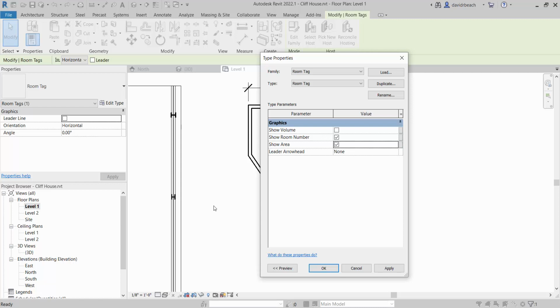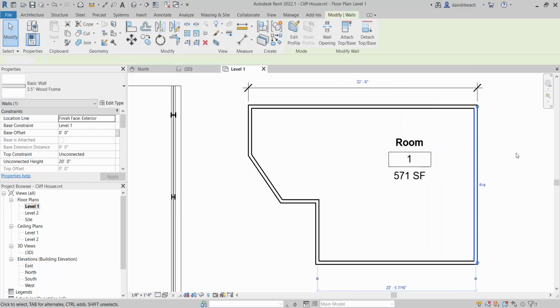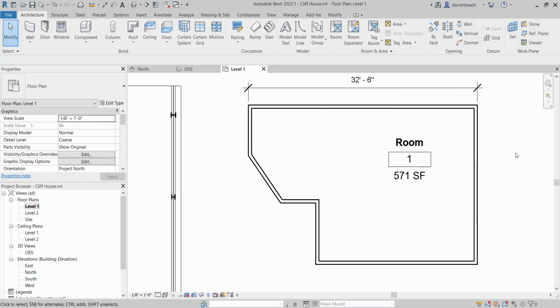Okay, so you guys are getting ready to go into some pretty hefty programming assignments in Studio where you are defining and editing a lot of square footage. Again, I'm not going to tell you to use Revit to complete your design this semester. I think that's a bad idea. But to help you complete some programming assignments, if I turn on room area, I now know that that space is 307 square feet. And I know if I move that wall around, it's going to automatically update my square footage based on the enclosure of that space, which is really handy when you're given a list of quantities to start defining and seeing how they're going to work.